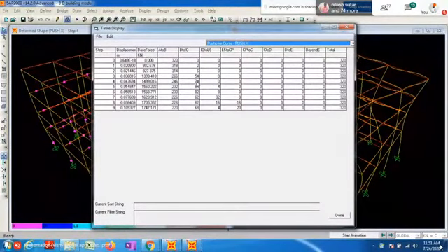Pushover analysis, then time history analysis, all of these give the performance after yielding. Sometimes you will get a number of hinges here also. That shows the building has collapsed. Then whatever element sizes we have provided are not sufficient. Then revise the sizes and make the building safe.